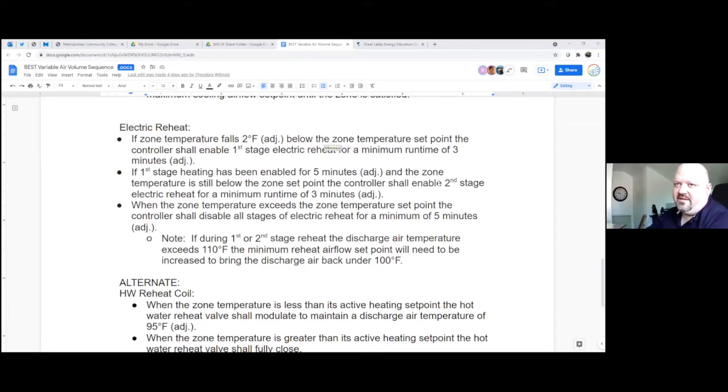And I think they've even changed since 07. I think there are even new requirements, but we could find that out. 2018, yeah, the 2018 requirements now. So again, it's not just 700 ppm above outside anymore. It depends on the space usage and all this stuff. And like we said, this conversation we're having is literally like a 2-day conversation. And then you calculate not only the requirements.